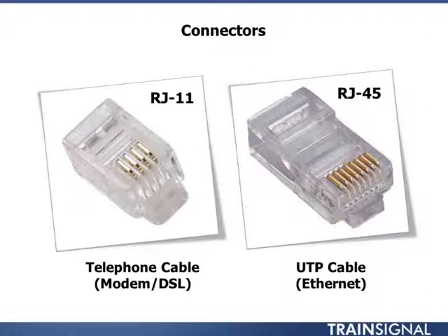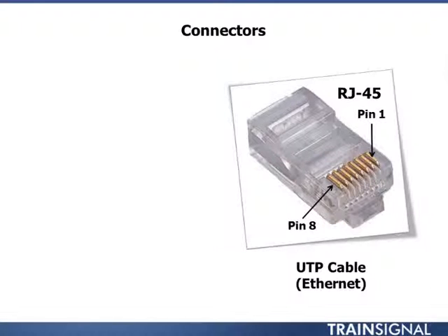Now, another type of cabling I just want to mention here is what's called plenum rated cabling. Usually the space above the ceiling, when you have suspended ceilings, facilitates airflow throughout the building, and you can actually put cabling there. And what plenum rating cable does is it can be installed there, and it has a fire retardant outer casing made of PVC. And non-plenum rating cables should not be used in the plenum area because of the type of fire risks that can be had.